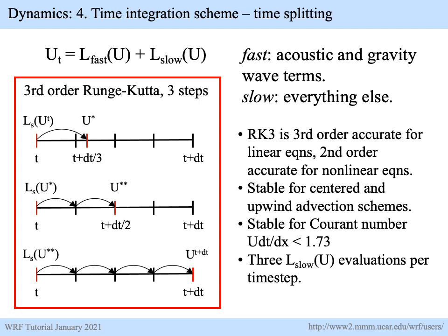This different integration method for the acoustic modes is combined with the Runge-Kutta time integration. It's contained within it. The equations depicted here in the red box, depicted pictorially, show the 3 time steps in the Runge-Kutta scheme. And it also shows inside those time steps are sub-steps where we integrate the fast mode terms, the acoustic mode terms, and evaluate them at every sub-step within a different integration scheme that's coupled with the Runge-Kutta scheme.